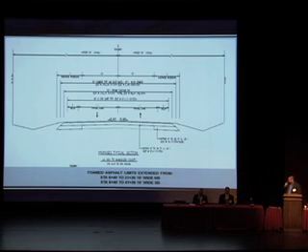So our typical section consisted of cutting down at the pavement edge. Our existing section was about 20 feet wide. We cut down, added 8 inches of type A grade 1 material on the edges, and cement treated that with 2% cement, and then we came across the top with 6 inches of type A grade 1. And that was our section in the other parts of the project. Of course, our new section consisted of the foamed asphalt, and we did that for an 11-inch depth. The station limits that we modified were from roughly station 840 to 4150 for a width of 30 feet.